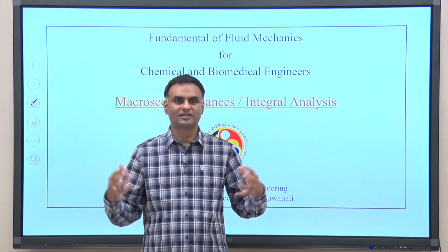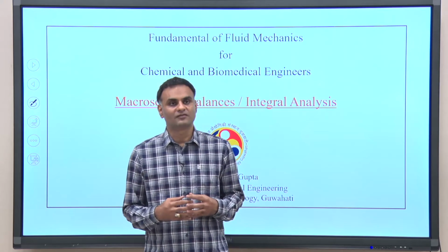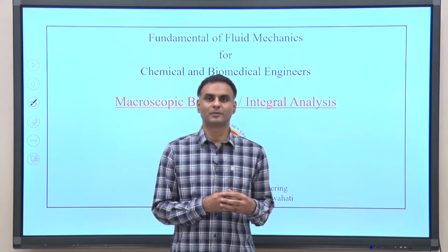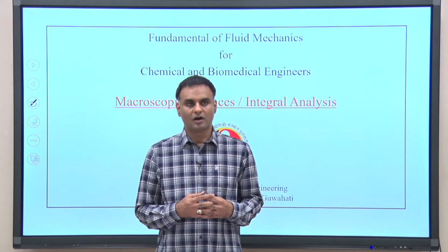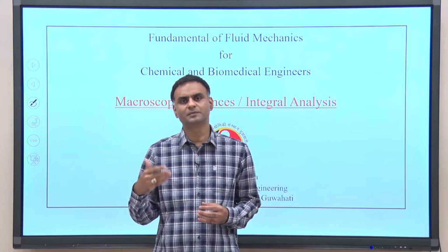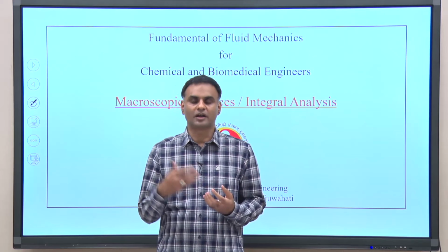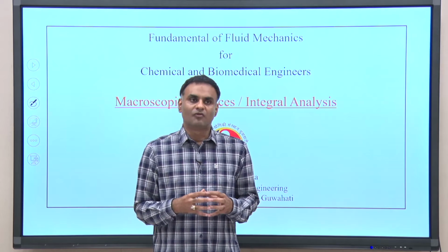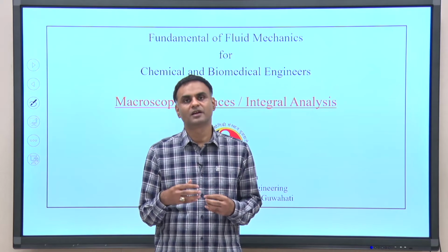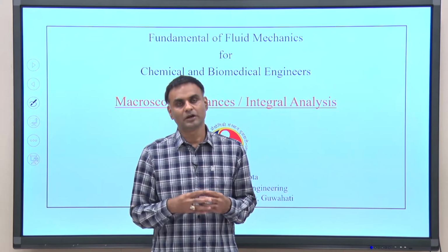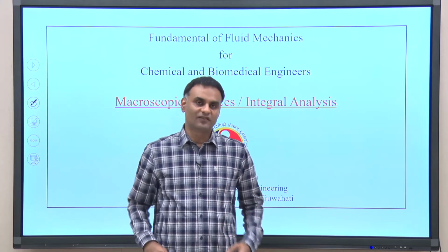When we identify the system or the flow domain, we can find out using macroscopic balances the force exerted on a particular body, or the force exerted by the fluid on a beam, on the pillar of a bridge, or on a car, etc. What we will be able to get is the integral of this force. We will not be able to get the distribution of the flow field or the distribution of the force on the surface, and that can be obtained using differential analysis.